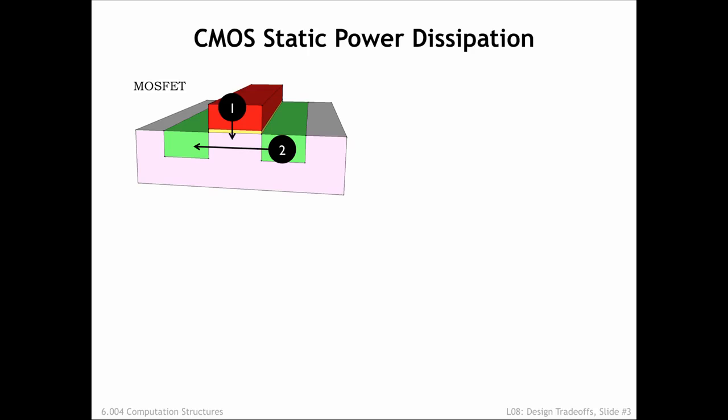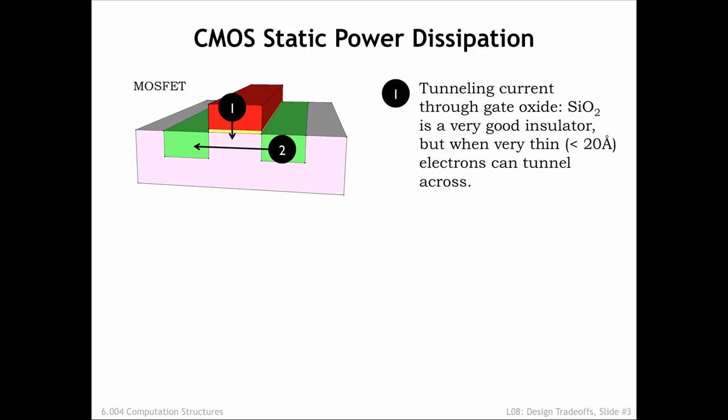We'll discuss the effects as they appear in N-channel MOSFETs, but keep in mind that they appear in P-channel MOSFETs too. The first effect depends on the thickness of the MOSFET's gate oxide, shown as the thin yellow layer in the MOSFET diagram on the left. In each new generation of integrated circuit technology, the thickness of this layer has shrunk as part of the general reduction in all the physical dimensions.